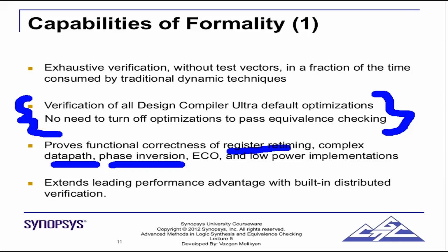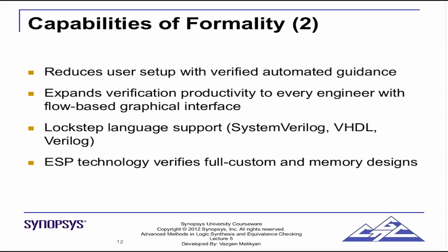Then if you're short on compute resources, you can use the distributed verification technique and split the load across different CPUs using Formality. Since it's very tightly integrated with Design Compiler.